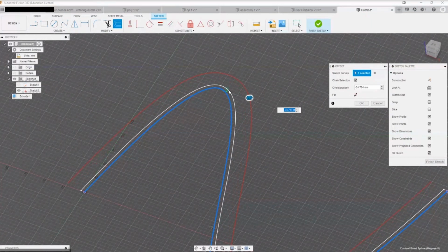And I think this is a bug in Fusion. They might need to fix it. So it's not going to let you offset something that's already been offset. So you need to always go from the original one. But this is only specific to this type of function. We're going to go something that's 5 millimeter offset. And then we want the next component to be 7.33, right?